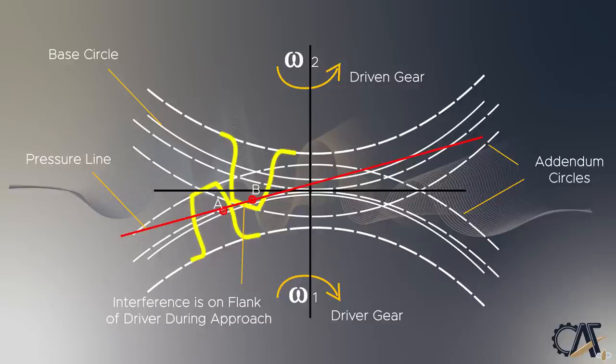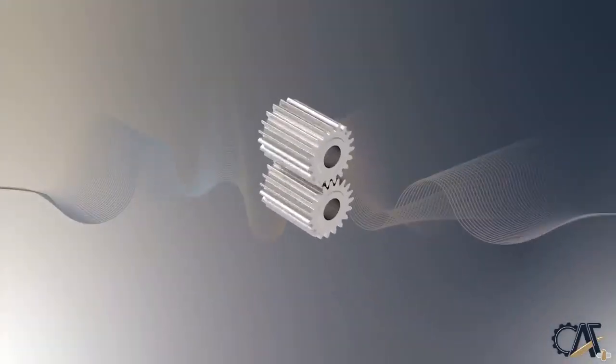However, it was recognized by the American Gear Manufacturers Association that a 20-degree pressure angle was more suited for most applications. The benefits of selecting a 20-degree pressure angle include additional power transmission capacity, better lubrication in the gear mesh, and reduced numbers of teeth for the pinion without undercutting. The 20-degree pressure angle gear tooth has a wider base that allows for additional load capacity, but it incurs additional wear on the tooth flank during the interchange of teeth in and out of meshing. For some special applications where noise is not an issue but strength is, a larger pressure angle of 25 and 30 degrees can be used.